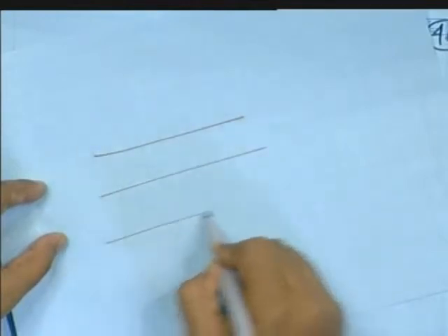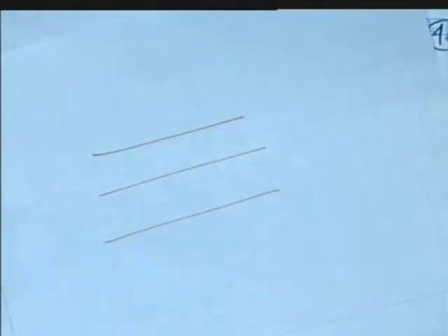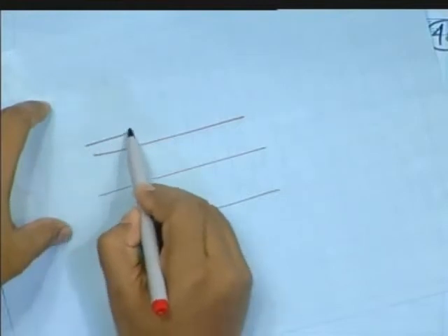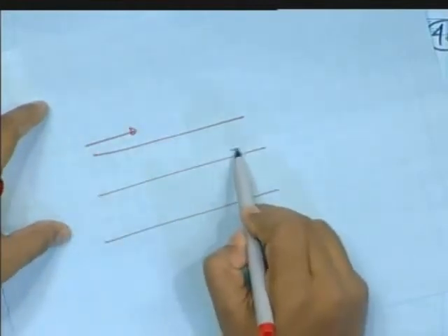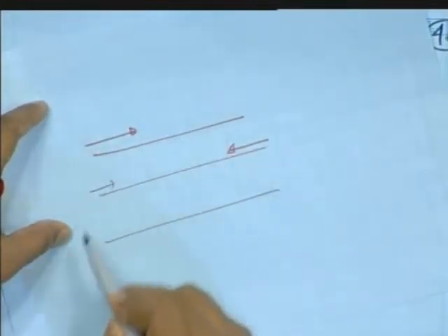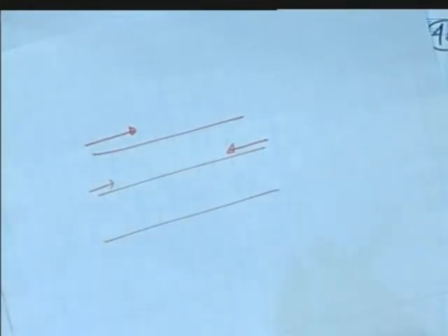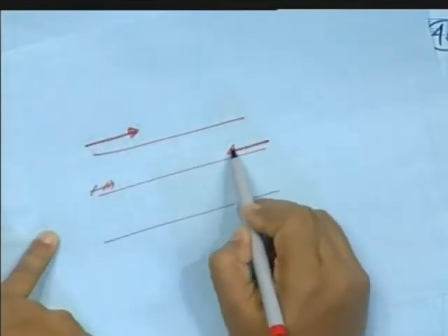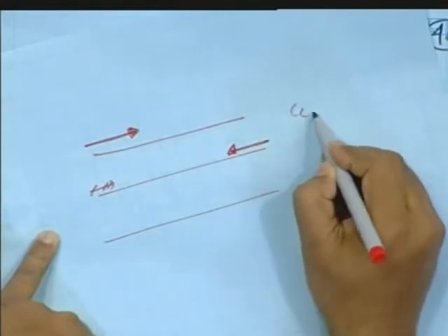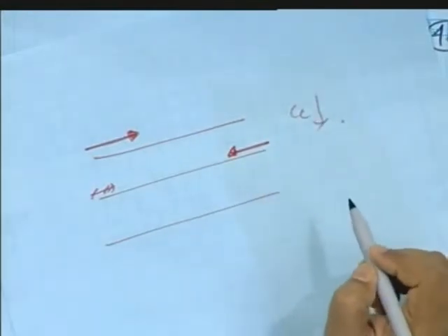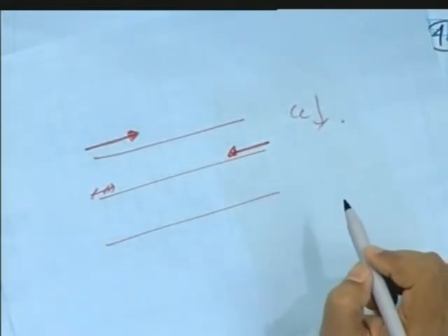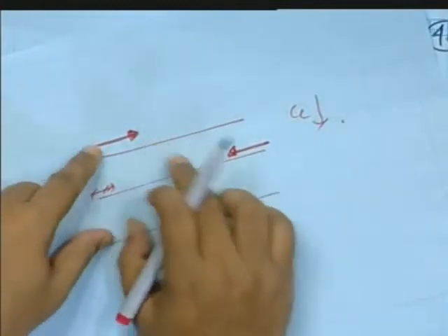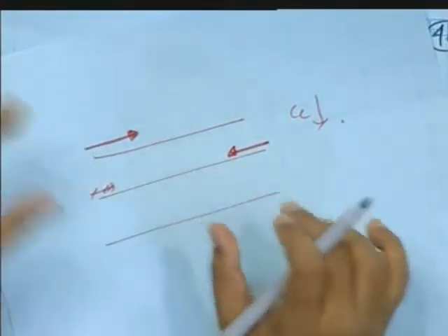Say you have multiple buses running. So 3 buses running. The signal can propagate from one to this direction, from here to here direction, or here to here. Both directions are possible. Sometimes, if you route your signal path so that one is propagating through this, and the other is propagating through this, the coupling capacitance reduces. What I am saying? See, this bus is consuming some more power. Lot of switching is there.